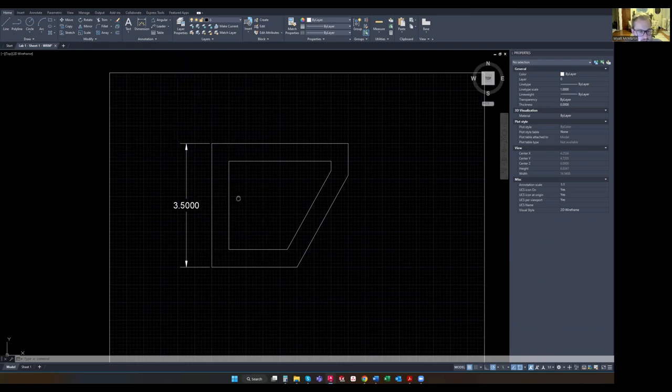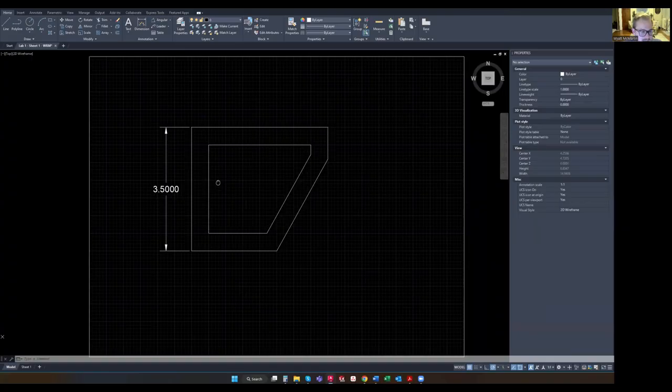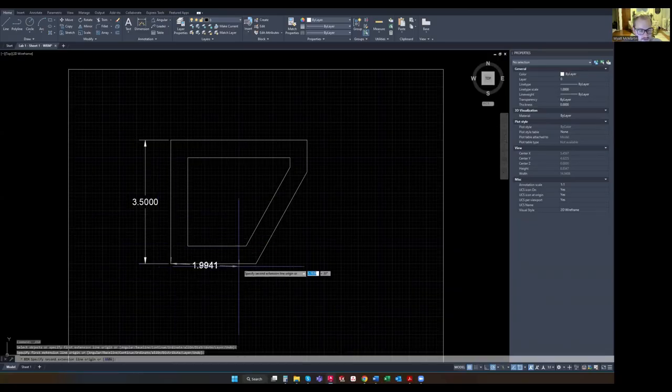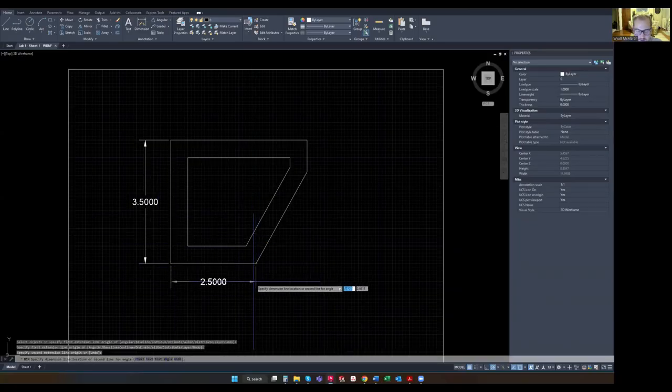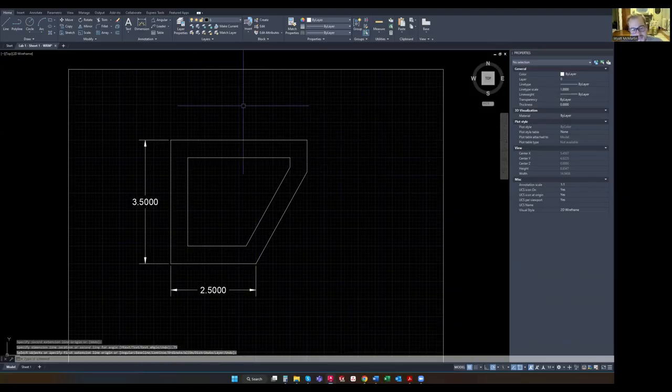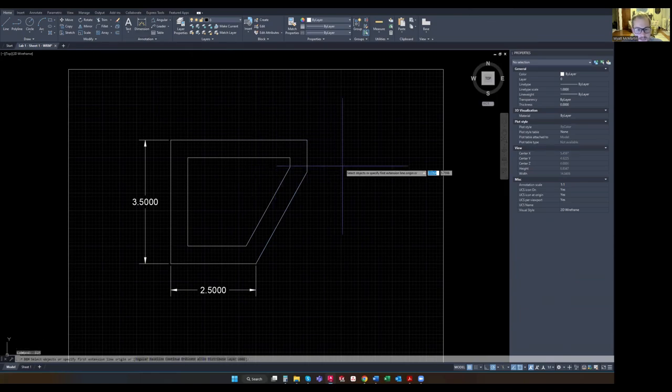What's cool about AutoCAD is the last command that we've executed is saved in memory. So while you can come up here and click dimension again and just do another dimension from here to here, drag it down before you click and then type 0.75, enter. But if I X'd out of that dimension, so now I'm not in my dimension tool anymore, I can't pull a dimension. Because that was the last tool that I used, I could just click the space bar and now I'm back